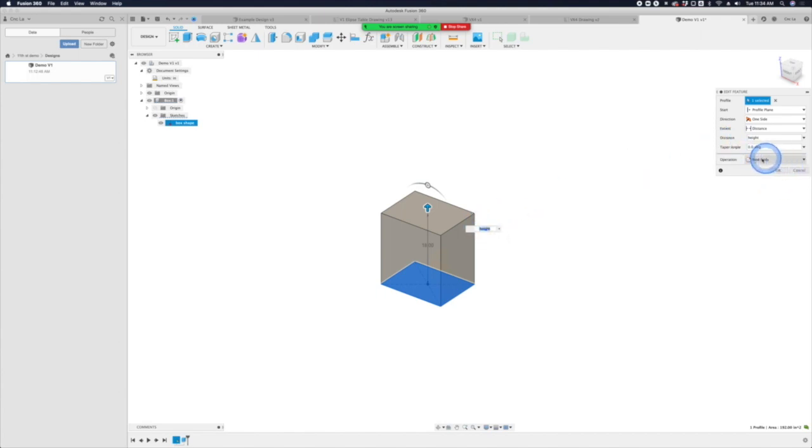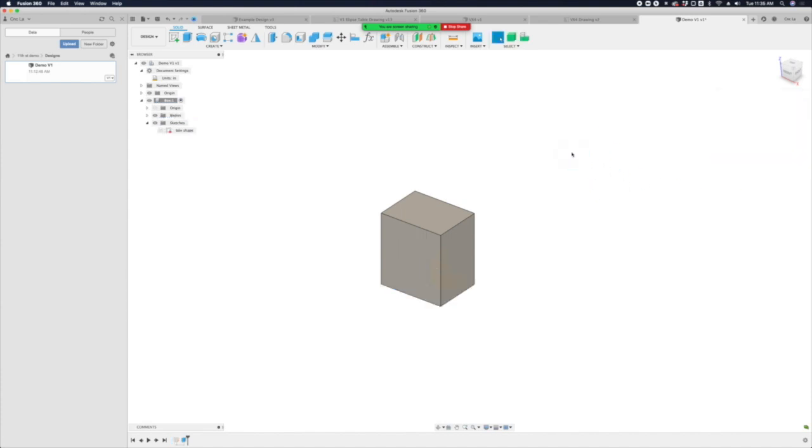The other thing that it does that you have to pay attention to is there are different modes, different methods of operation. If you have more geometry in the space, sometimes this will join to something you already have existing. You can use this to cut volumes from other shapes, you can use it to intersect where only the overlapping parts remain, or you can create a new body. The funky thing is you can only create a new component the first time you extrude this.